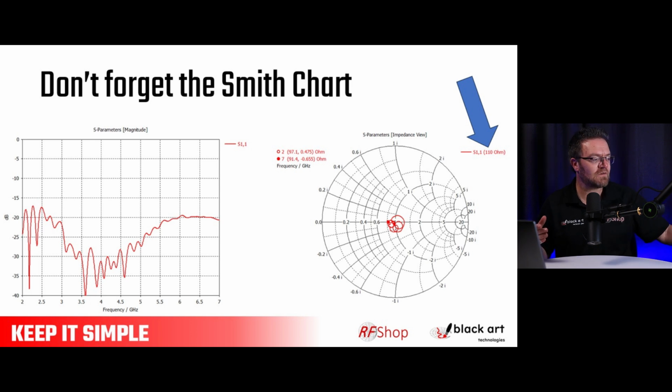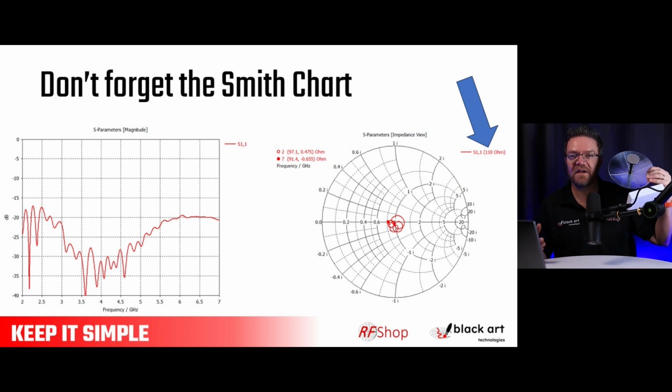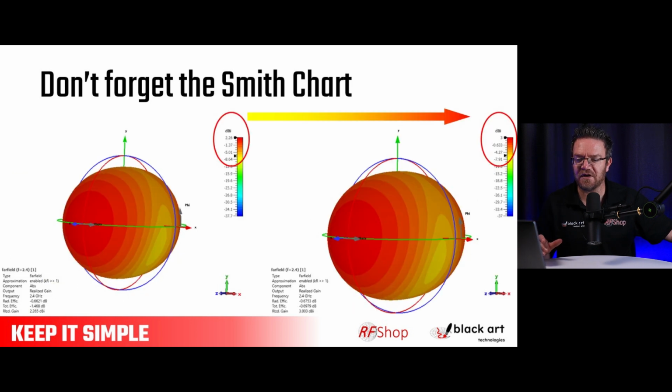This little spiral here doesn't have a lot of value yet unless it gets placed somewhere where it can be meaningfully directed in a direction. So it's just doing two directions. But if I just went for the original design, it had 2.2, almost 2.26 dBi gain. Was okay, like a dipole, cool, can live with that.